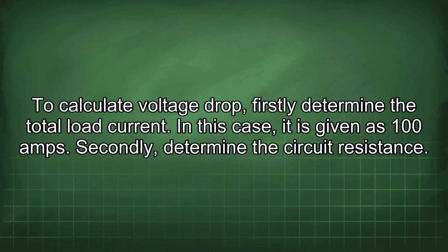To calculate voltage drop, firstly determine the total load current. In this case, it is given as 100 amps. Secondly, determine the circuit resistance.